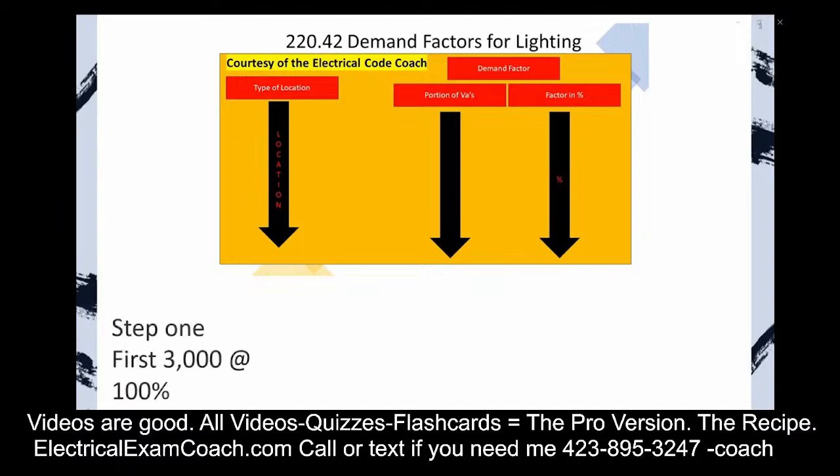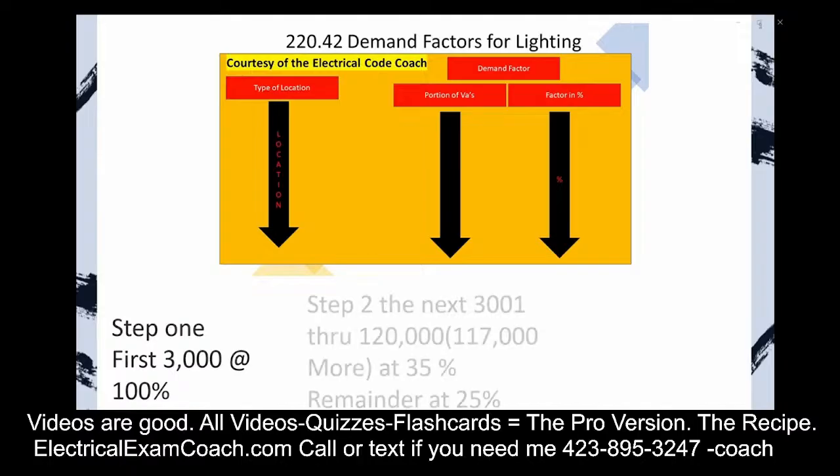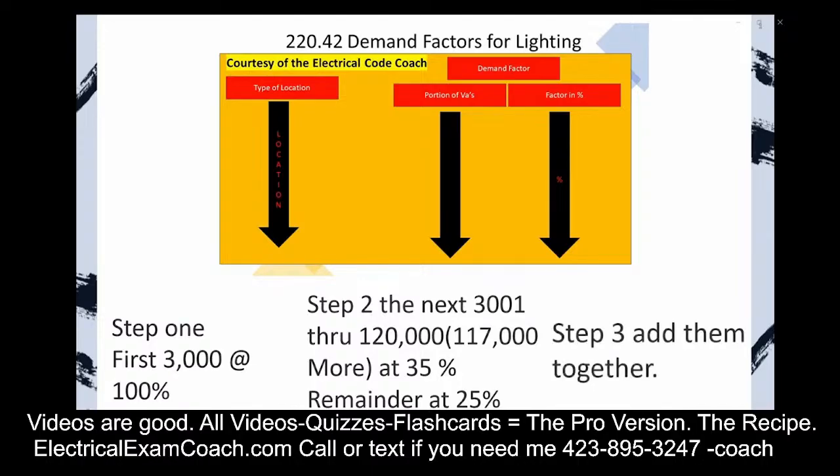Step one, we're going to take the first 3,000 VAs at 100%. Step two, we're going to take in between 3,001 through 120,000, which is technically just another 117,000 more. And that's how I'm going to refer to it for the rest of the program. We're going to take that percentage at 35%, and then we're going to take anything above and beyond that at 25%. Then step three, we add them back together. We take the original 3,000 that we set to the side. Then we're going to take that new reduced load, add those two together, and that's going to give us our total load.